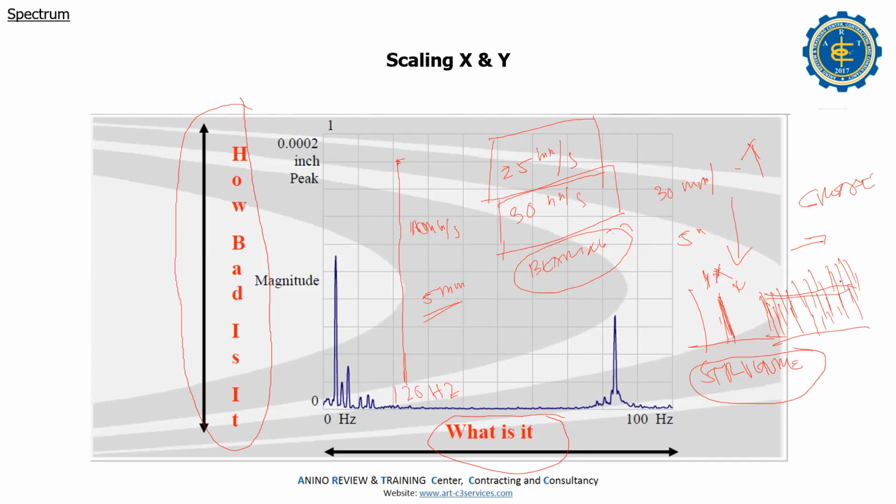So meaning, for a long time they did not grease. It's a lubrication problem, a lubrication issue. But don't worry about this 1x, because 1x is not the fan issue, it's the structure. If it does not go down, 1x could be unbalance also, right? Unbalance, you can monitor.